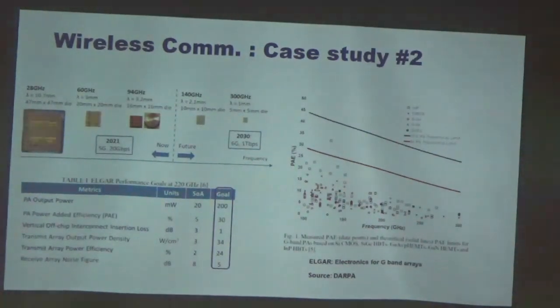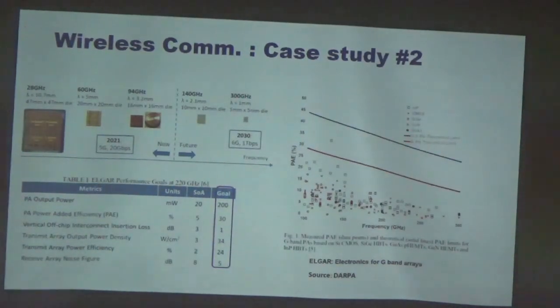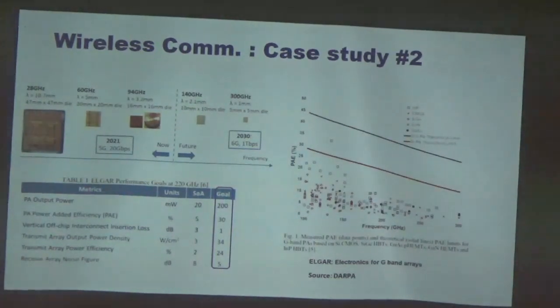So you heard about terahertz design, sub-terahertz design, imaging. Different applications are coming for wireless imaging and all those. They are going to operate at the D band, somewhere around 80-90 GHz. And at those frequencies, the power amplifier is the key limiting block, where you cannot achieve more efficiency and more output power.